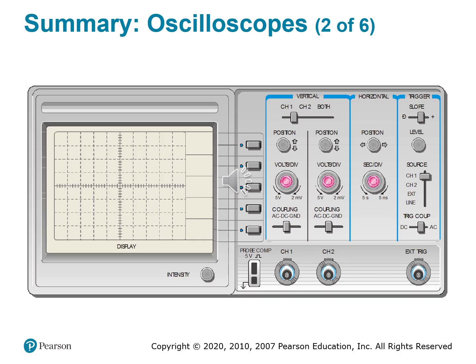So let's get hands-on with the front panel of the oscilloscope. So you see here the oscilloscope's internal structure. And let's go ahead and take a better look at the front panel. This is where the magic happens, where you take control of the signal you're observing. We can take a guided tour across the scope interface. We can look at the vertical section, that left center, and this section controls each input channel. So channel 1 and channel 2, or more channels if you have them on your actual scope.